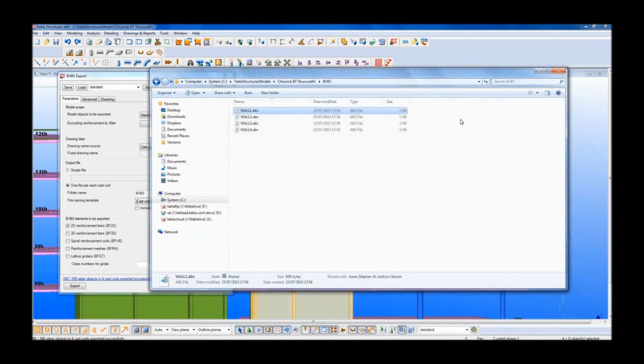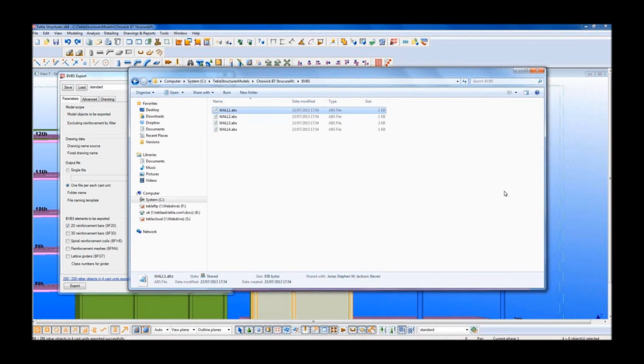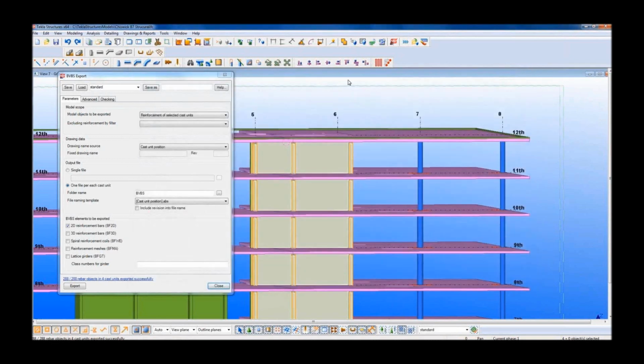And effectively what it means is it's given us the same sort of security that the structural steel fabricators have, that they do the model, they export directly from that model. So instead of having somebody typing in from Excel sheets manually, where it's quite easy to just hit the wrong key and then it gets to site and it's the wrong size, we've totally negated that. And also because of this, if the contractor's got the model, he can do his own call-offs from the model without having to go through hundreds of drawings. He can just pick certain bits and say, call me that off, or call me this off, and have it delivered to site, and even do 4D to that as well.